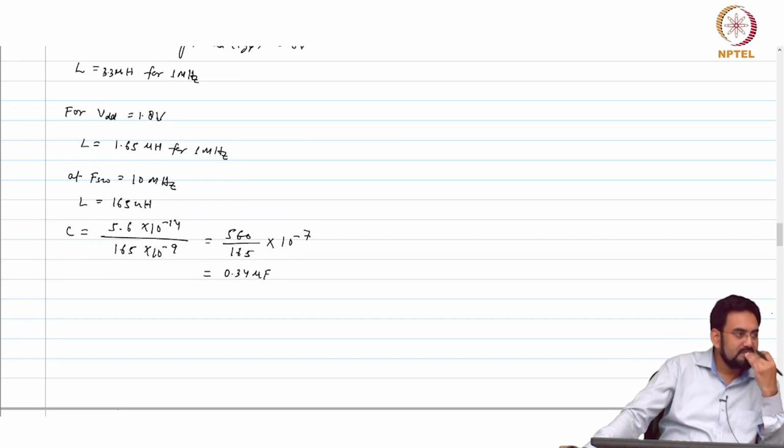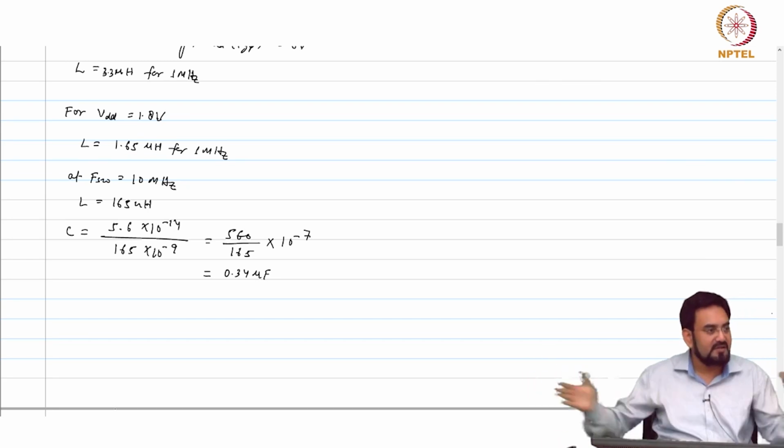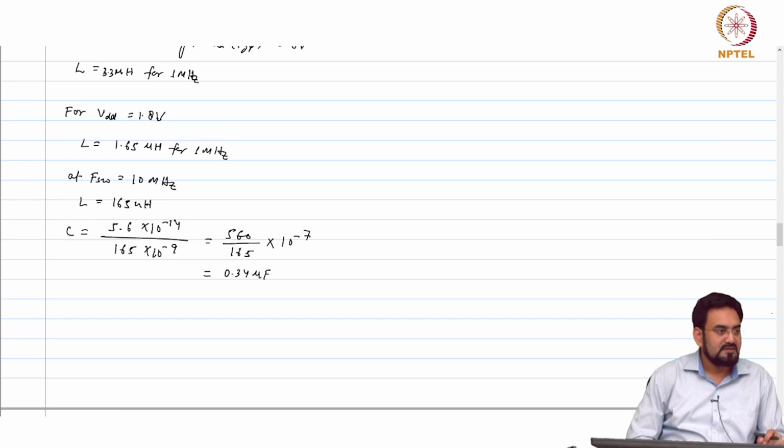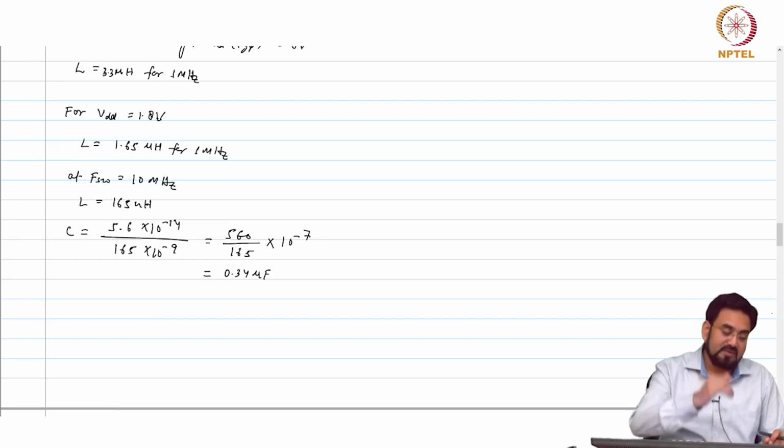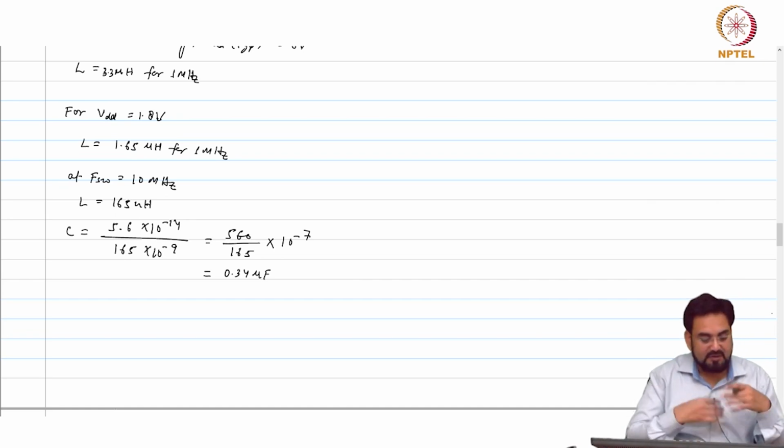500 milliamp kind of thing? How much? Actually, V in minus V out by L, how much is that? So, you have to multiply that by your time. So, let us say you stretch your duty cycle to 100%. So, 100 nano. So, how much will it rise in 100 nanosecond? You have to multiply into the time. Yeah, 5.45 milliamp.